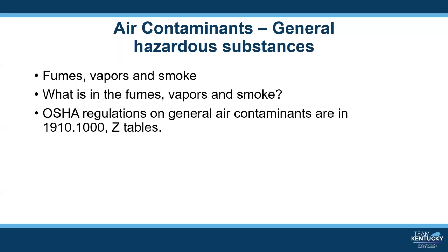A smoke is an airborne particle from something other than metal that is burned. This creates a visible suspension of carbon and other particles in the air, typically one emitted from a burning substance. We typically call something smoke when it looks like smoke. All welding processes emit fumes, whether it's MIG, TIG, stick, torch, laser, and/or plasma torch welding. The hazards of each are different.